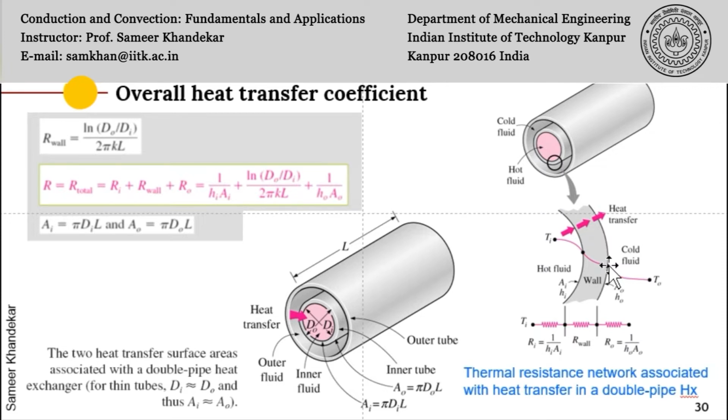You will recall the diagrams which I showed you. In many cases, we would like to, of course, reduce this thermal resistance. So one of the ways of reducing it is to make this wall made up of copper, for example, or some good thermally conductive material, and as thin as possible, so that it is able to take the pressure and the other mechanical loads which are coming.